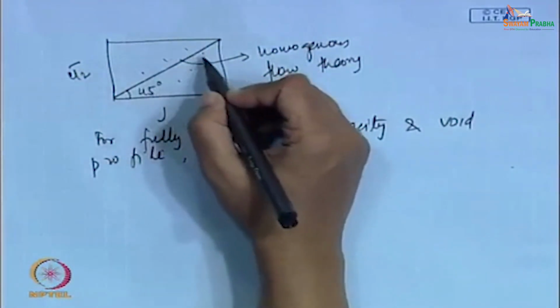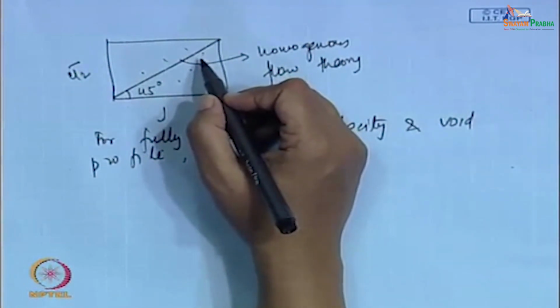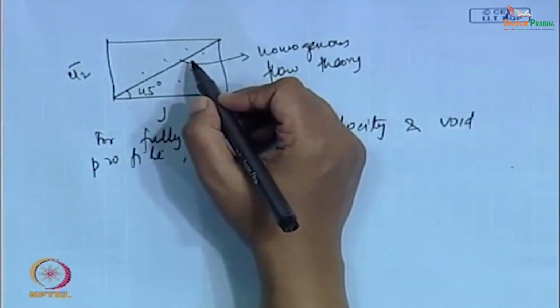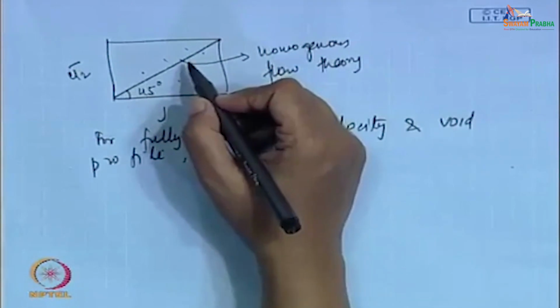The amount of spread it has from this line tells us how much it has deviated from the homogeneous flow theory, and whether we should go for some correction or not, and in what way we should introduce the correction, whether C0 is important or whether J21 is important. Usually we find that J21 is important and some particular J21 has to be incorporated there. Correct?